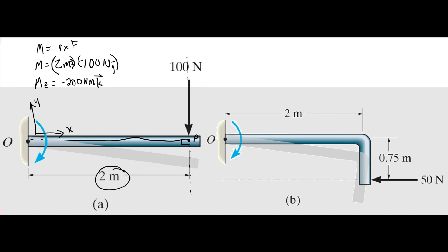That means that if you use the right-hand rule here, you can put your thumb out of plane and curl your fingers in the direction that the 100 Newton load would apply at point O to make that beam deflect downward like is shown here. So when you see that beam deflection downward, it's making it curl in that direction.